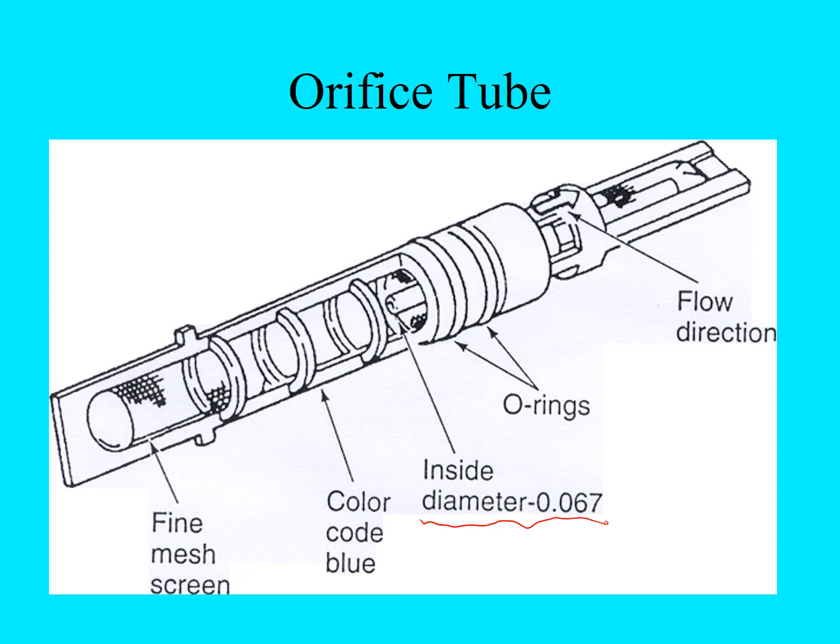It does have a direction of flow, so refrigerant is coming in on this end where we have the most screening, so that it won't plug up, and then it goes through the orifice, and on this side low pressure, low temperature liquid is coming out.